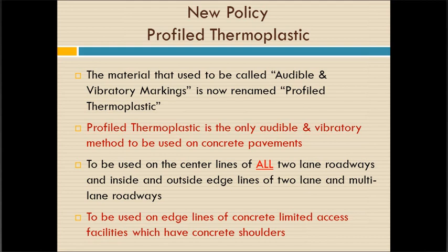Now, if you're dealing with a concrete road, then you're going to put profile thermoplastic on the center lines of all those 2-lane concrete roads.